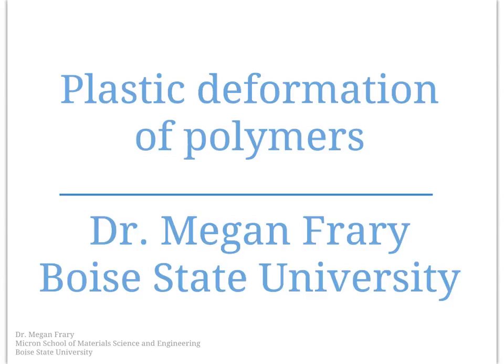In this video, we're going to talk about the plastic deformation of polymers. As with most parts of polymer mechanical properties, this depends strongly on temperature, and that's because obstacles must be overcome for plastic deformation to occur, and those obstacles are more easily overcome as the temperature is higher.